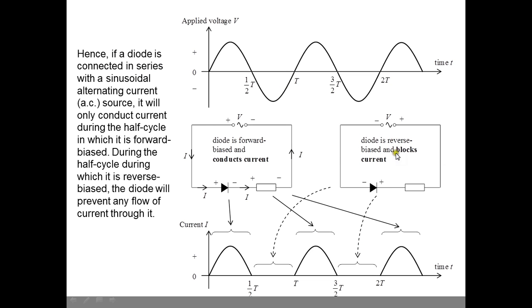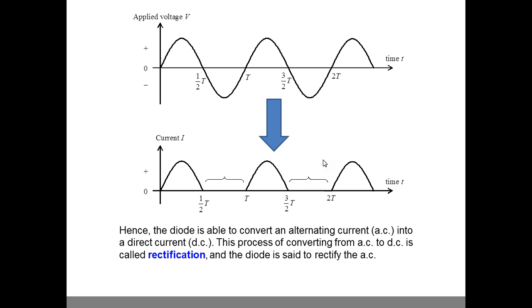So if we include a diode in an alternating voltage, with an alternating EMF, and the voltage looks like a waveform like this over time, when the diode is applied, we will only have the voltages or the current in the positive, forward biased direction. Simply, this means that everything below the zero line, anything with a negative current, will be removed. This is what we call rectification, and more specifically, half-wave rectification with a diode.